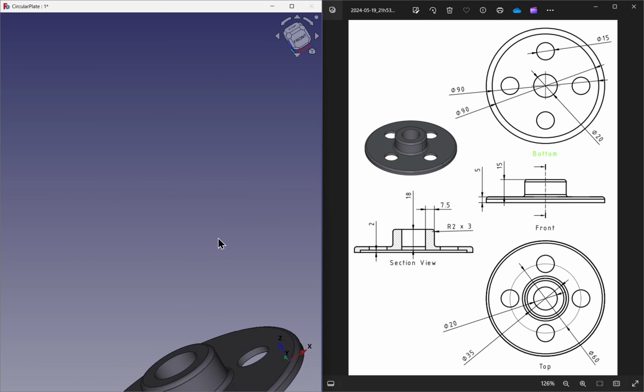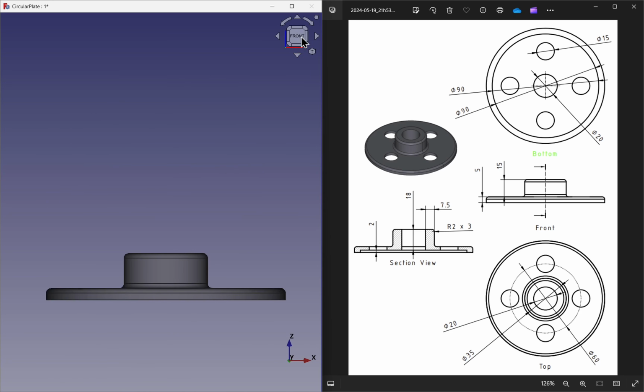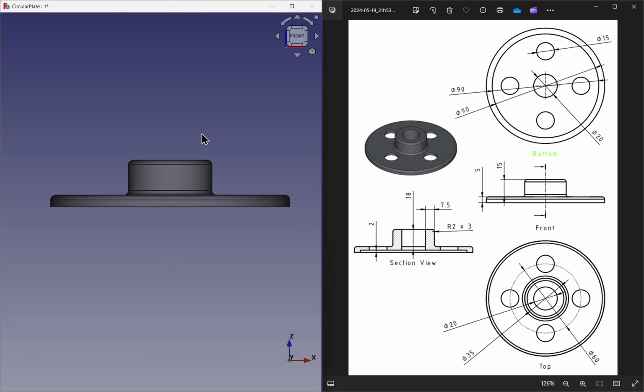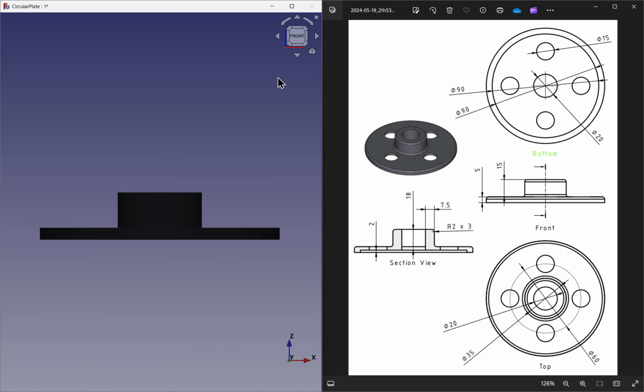From the front or side views, this form is much simpler, almost like two stacked rectangles if you ignore the curved corners. If you can't imagine a subject in less detail, then one trick is to look at the subject and squint your eyes. Blurring out these features helps us to focus on the core structure. We end up with stacked sections that can be created as layers of extrusions. This blocky first, details later approach is common in CAD. It lets us define the main volume before adding refinements.